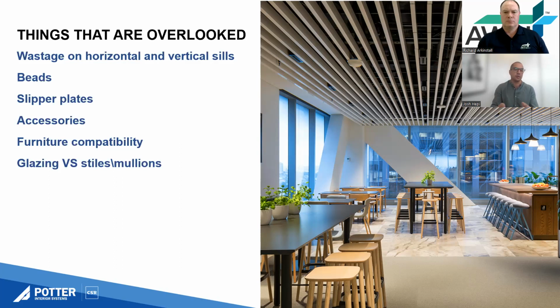And where that might trip you up is if the detail shows 75mm, but the architect or designer's called out 10mm glazing. It's very hard to make it work. There are ways around it, but it doesn't always work out well, and that could become your problem later. So if you can pick it up at the tender stage, perfect.